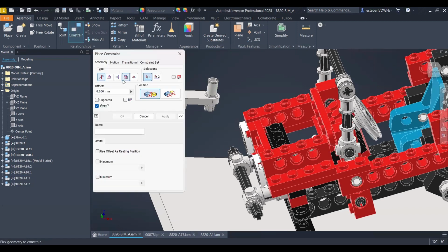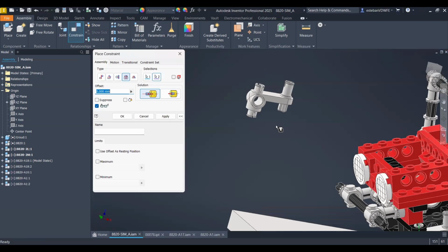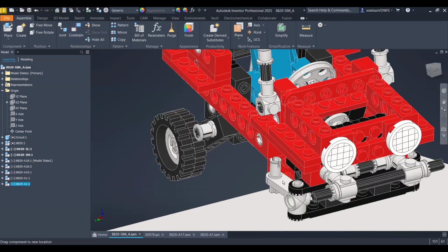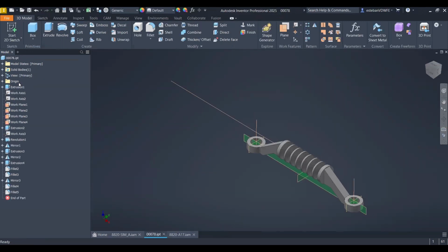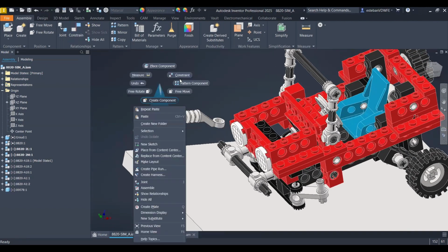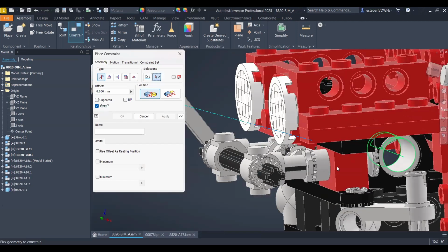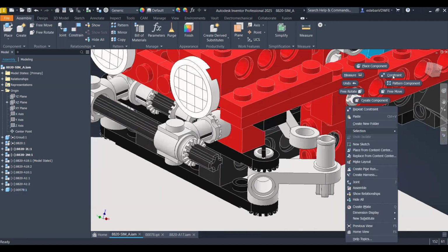It will be the steering system with the steering wheel and the axis, and these other two pieces for the pivoting of the wheels. There you go. Then we have the rack, and that rack is going to be concentric with the corresponding geometry in the steering system, and it should be pivoting like I'm showing right now.